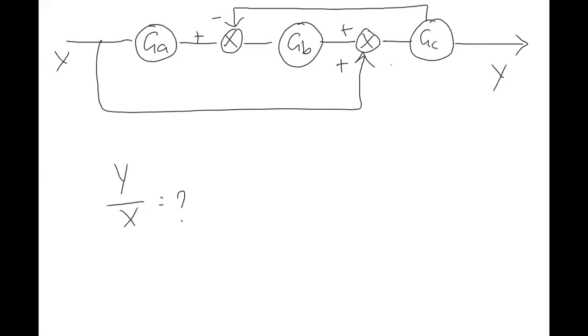The reason is that this is a feedback loop, but you have a connection which is joining in between. That is why this is not a standard loop. So you have to assign the variables and derive the transfer function.